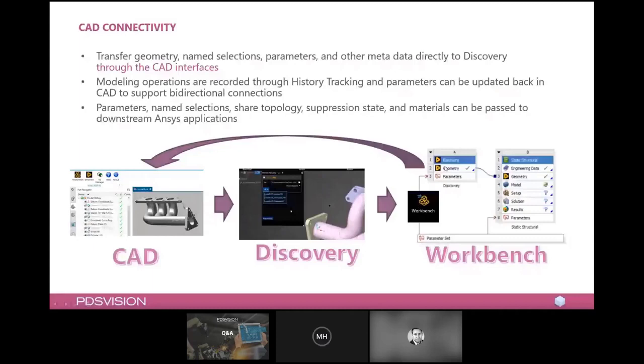and then you go for static structural, and surprisingly, you also have the same dimension in here, which enables you to run this on Ansys Mechanical. And if you have some results like maximum stress or displacement, you can add that as a second parameter. Now you can launch a parameter study which varies the 3D CAD geometry, pushes it all the way through Ansys Mechanical, and you get the full-blown results in here. So you are able to drive your CAD geometry from Ansys Mechanical via Discovery. And that's a very nice option as well.